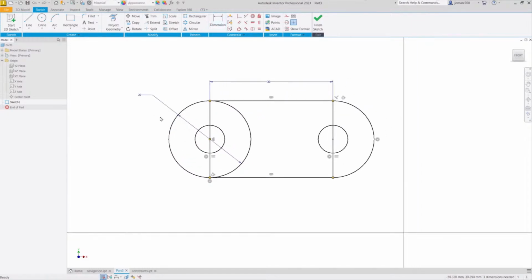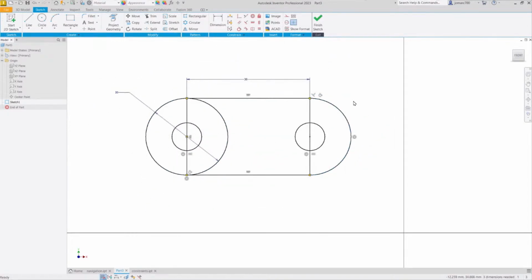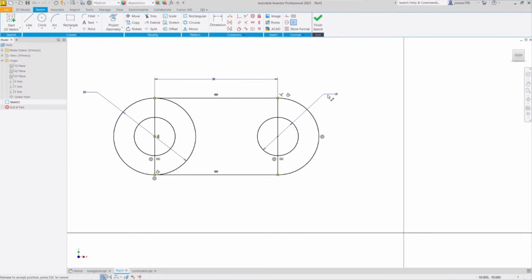Let's try to resize our geometry. Let me grab this circle and try to move this. Let's try to move this circle. So notice this one needs to be defined. Hitting D for dimension. Selecting this circle. Left click here. Target diameter to be 10. Selecting the green check mark. Hitting escape. Inspecting.